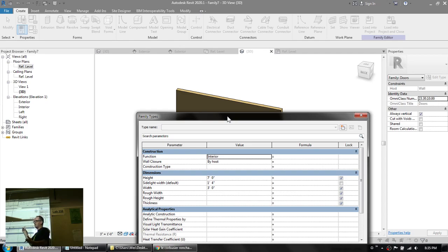So do you need to pre-make the family types in your family? No. Just make one, save it, good to go. So family types isn't actually used for making family types. It's used so we can modify the values and rename our parameter names if we spell them wrong.